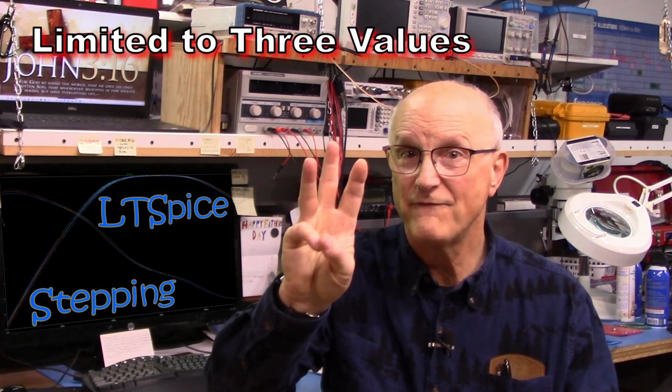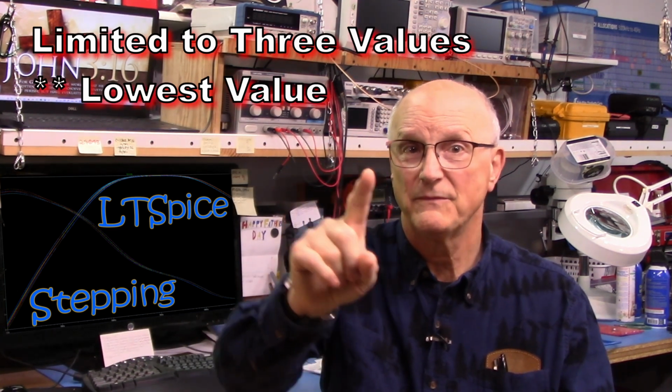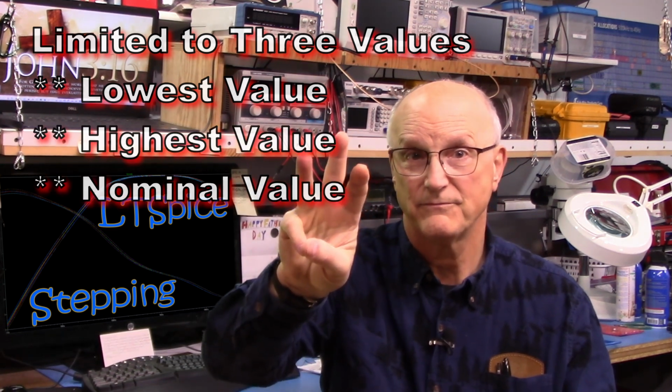As such, you are limited to only 3 values for each component: the lowest value, the highest value, and the nominal value. Now, it will simulate every possible combination of the maximum and minimum values of every component you specify. Then, in one last run after this, it will simulate the results of the nominal values alone.